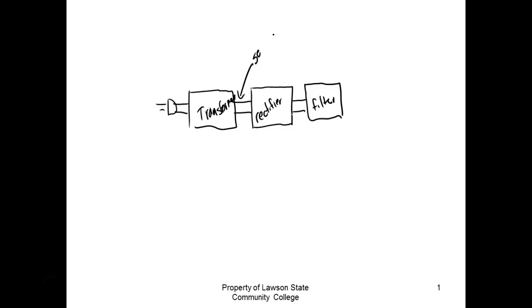So what is Alabama Power selling you? Power. And they're trying to get that power from their plant to your house, and they're trying to send it through wires. Now, what's the problem with wires? Yeah, they have an R. So V is equal to I times R. There's no such thing as a conductor that has no R. You understand that? So what happens in transmission, they call it line loss. This is how much loss you get in the lines just trying to get it from the power plant to your house, right? And here in this college, we're on TVA.